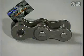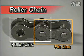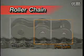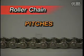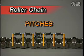A roller chain is made up of two kinds of links, roller links and pin links, that are alternately spaced throughout the length of the chain. When assembled, the roller chain is measured and identified in pitches. The center distance from one hinged pin to the next is defined as the pitch of the chain. All chain installations require the exact number of pitches before the chain can be sized and installed.